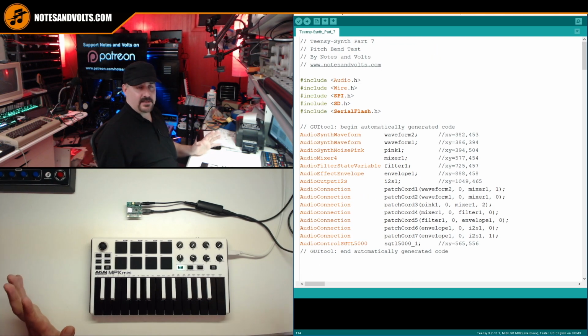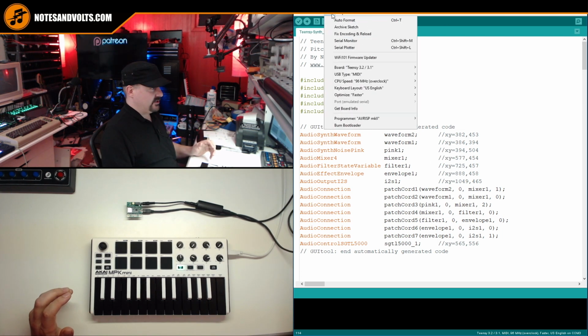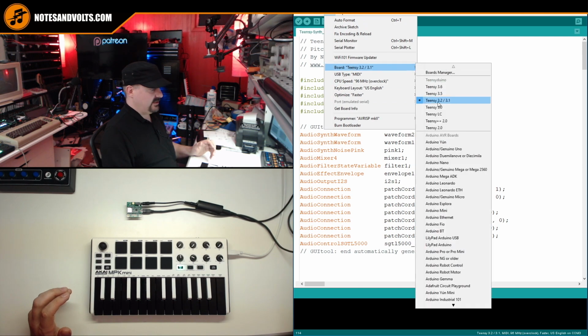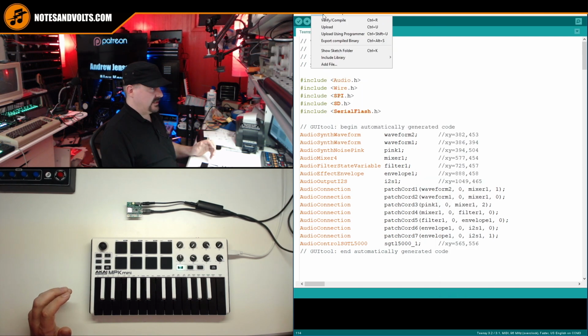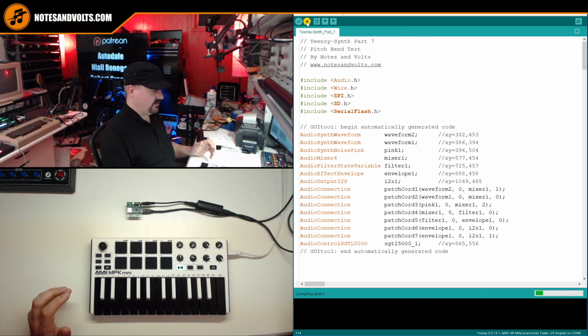That's a lot of math. Hopefully it wasn't too painful, but if you don't care about any of that, all you need to do is download this program, set your board type to Teensy 3.2, set your USB type to Midi, and upload it to the board.